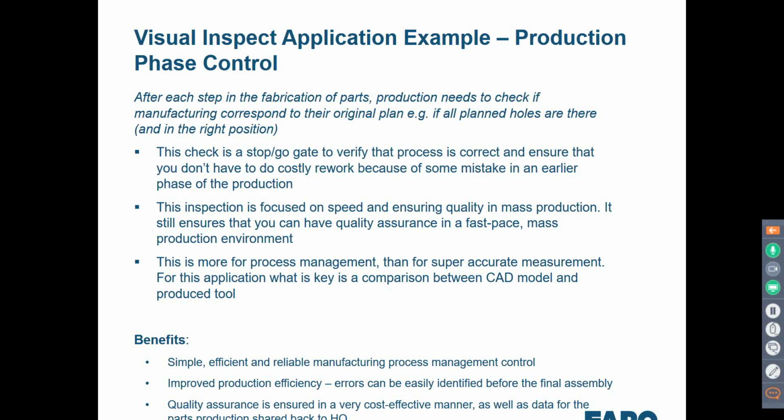I had the example about a shadow box where 30 weldment parts are put on a subassembly and everything's cleared, and the operator thinks, okay, I've done my job. However, if we can do a very quick pre-check before they even put those parts on, number one, we know the parts are good parts. Then we can do a quick in-process go, no-go check. Did they place everything, and did they place it in the right location? So this is very simple, very efficient, and very reliable.